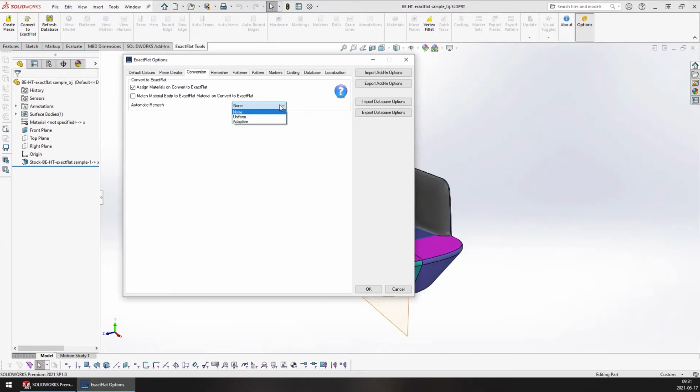So you have no idea if it's a high quality mesh or if there are any kind of meshing errors that may be translated downstream. If you know that your meshes are always going to be a good mesh, if your parts are always very similar, then you can turn this on and it will save you a little bit of time. However, it's a good idea to check your meshes right from the SolidWorks mesh all the way down, just to make sure that you have a good high quality mesh.